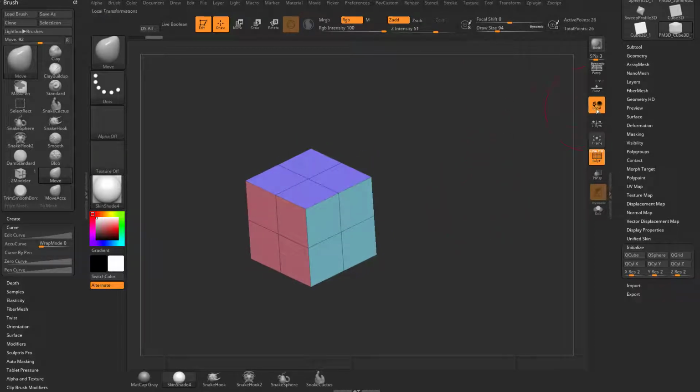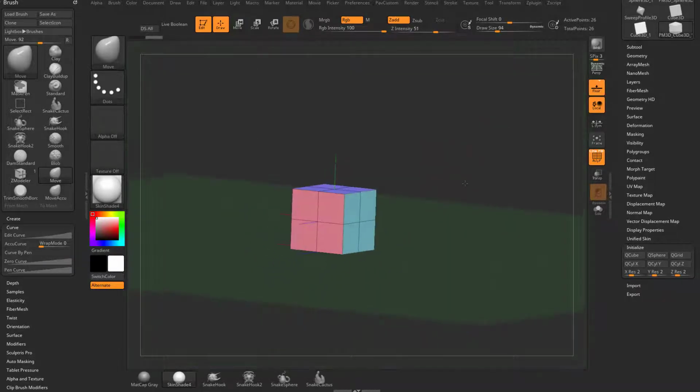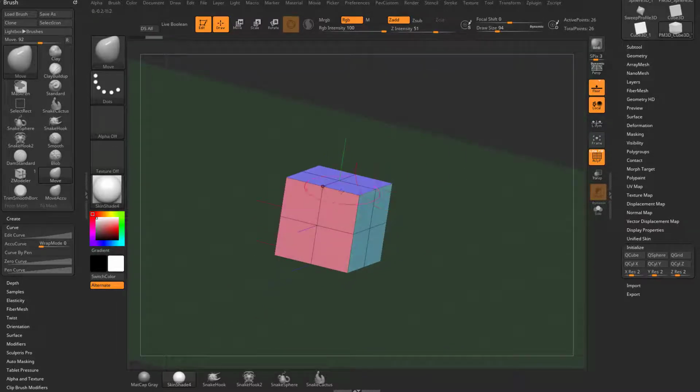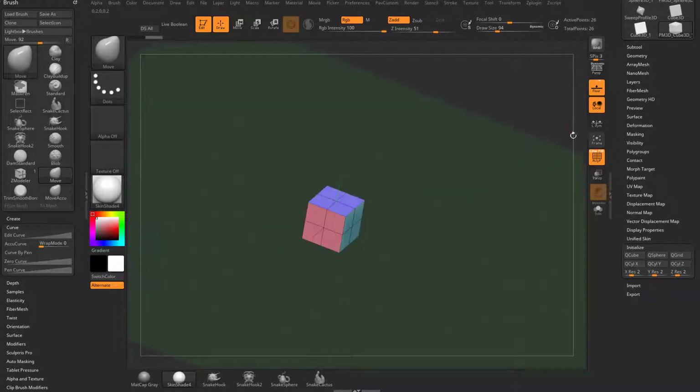So we've already talked about the axes. If I turn on my floor here, you're going to see the blue line is Z forward, the green line is Y up. Here's our floor plane, which we have right here turned on. We can turn on X, Y, and Z planes. But for the most part, you just have your Y plane, which represents your ground plane or where your object sits on top of. Z is where it faces forward. Y is up, and then X is on either side. Negative X, for example, negative X here, and then positive X on this side.